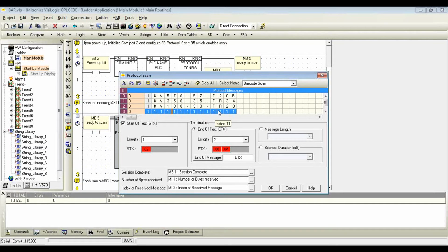It's important to note how the controller recognizes messages. The controller is going to begin at the top and work its way downward. So if I scan the first barcode in the list here, the controller will recognize it is, in fact, this barcode, and it will not travel down the list, even though this barcode would also fit into my variable. Again, it doesn't get that far because it recognizes a valid message above the variable. We want to keep this in mind when we are writing our incoming messages. We don't want to put our variable at the top.